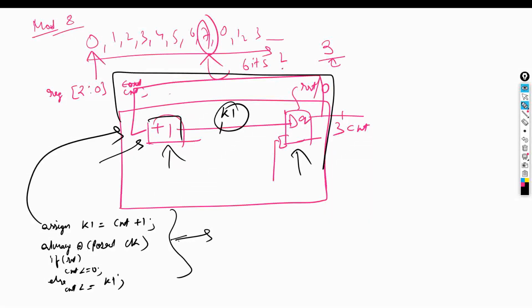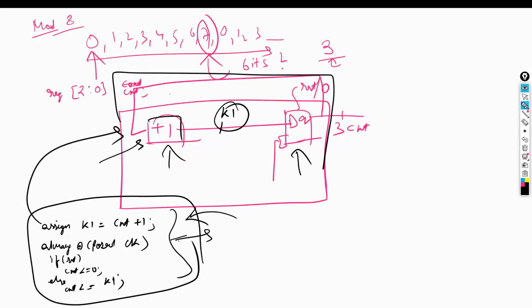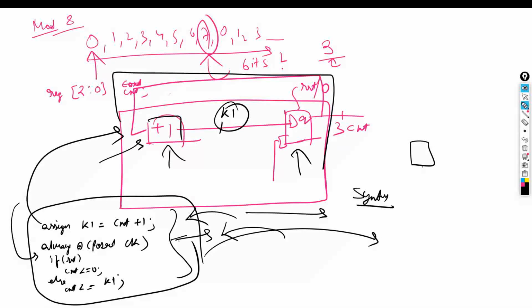Now this RTL code, we'll simulate it. We'll write a test bench around it to test it. And now companies are also using formal verification tools. We'll not be doing it here, but we also have a formal stage as well. In order to catch the bug and resolve it, that is what we do in this simulation stage or design verification stage. Once the RTL is clean, we'll send it to synthesis. Whatever standard cells we have, we'll use the standard cells and translate into a netlist. Let us first do this part.